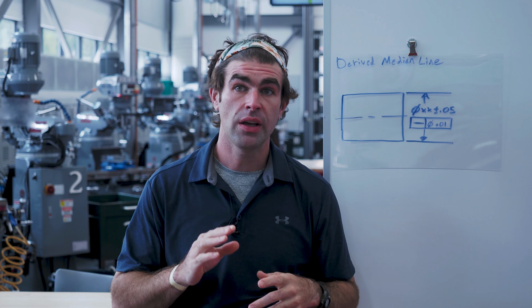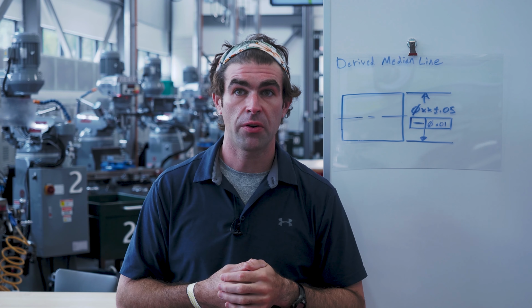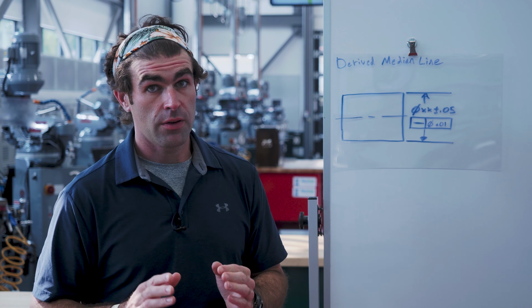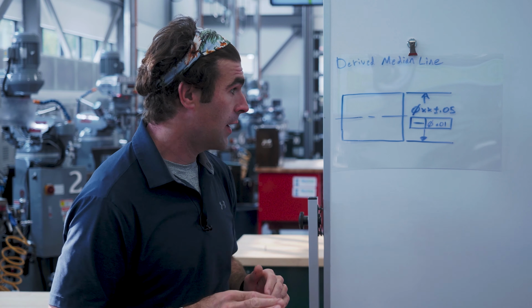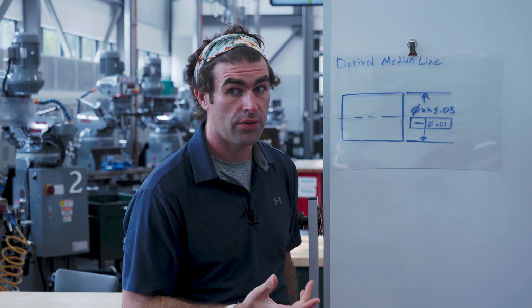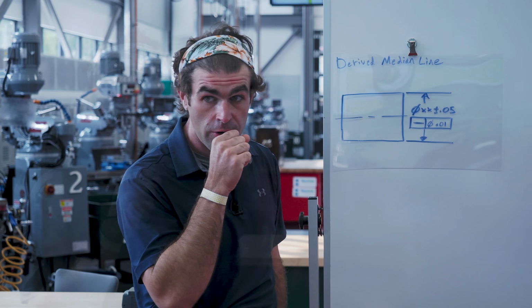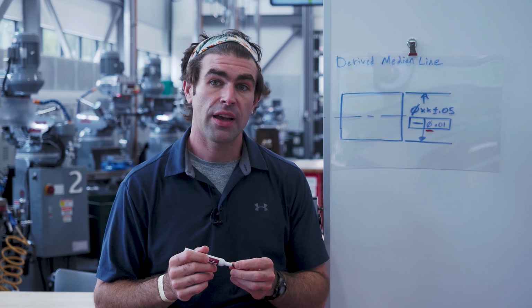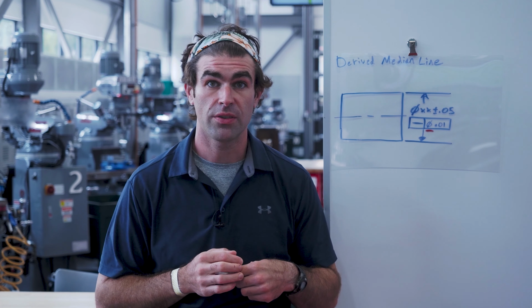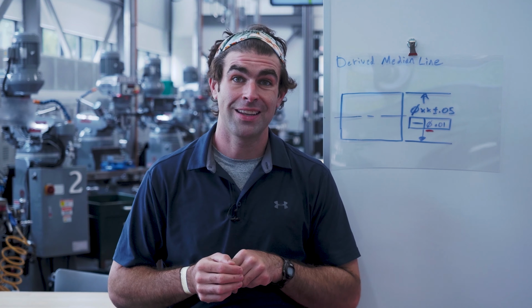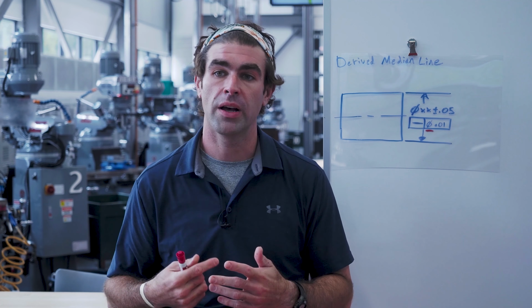So our last use of straightness tolerance is the derived median line straightness. So there's a couple giveaways that this is different than the ones we talked about before. It's doing a different thing. So first, it's going to be adjacent to the size dimension. So usually just tucked right under it. If you notice, we have a diameter symbol in there. That's a giveaway as to the shape of the tolerance zone. It's letting us know it's a cylindrical tolerance zone in which the derived median line of this cylinder must lie.